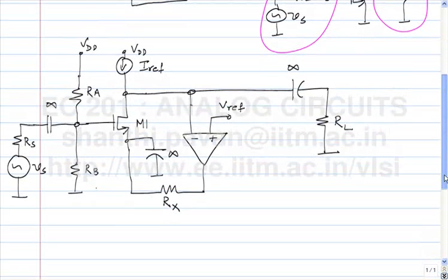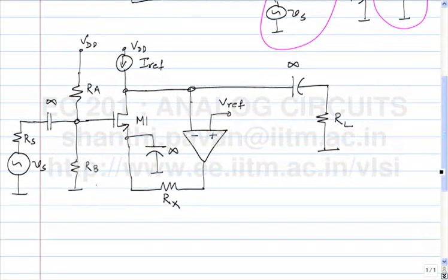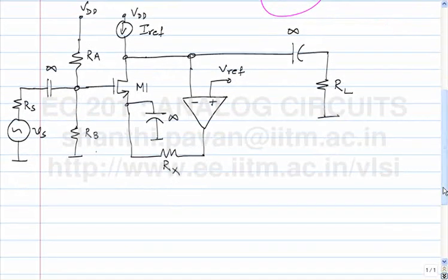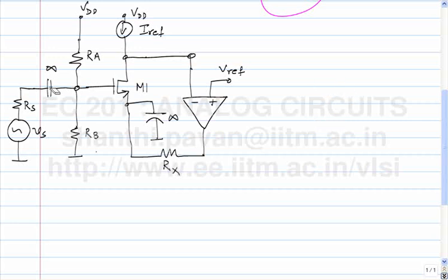Now, if the circuit was given to you, the first thing you would want to do would be to find the gain, alright, but before you find the gain, what should you do? Operating point. So let's try and take this whole thing upside down and try and compute the operating point. For operating point, what all go away? For computing the operating point, what is the circuit? This goes away, this goes away, this goes away, because there is no current flowing through this capacitor anyway, and this is what the circuit reduces to for computing the operating point.